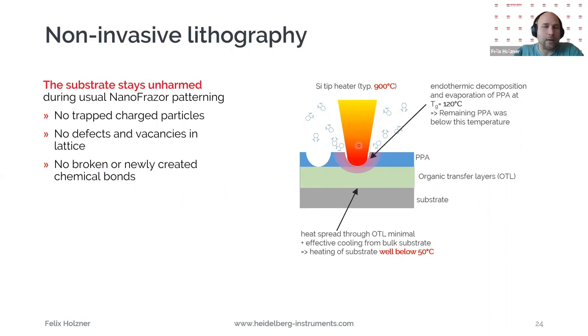And we actually don't damage the substrate below. I mean, we have people who are afraid that with our hot tip, you would actually damage a sensitive material here. But also in a separate webinar, we will cover this whole topic of how hot it actually gets here, what's the temperature here, and what's the temperature here where your sensitive material might be. And you will see this is not heating up, maybe not even to 10 degrees or so. That's not heating up here. It's only heating up the resist on top.